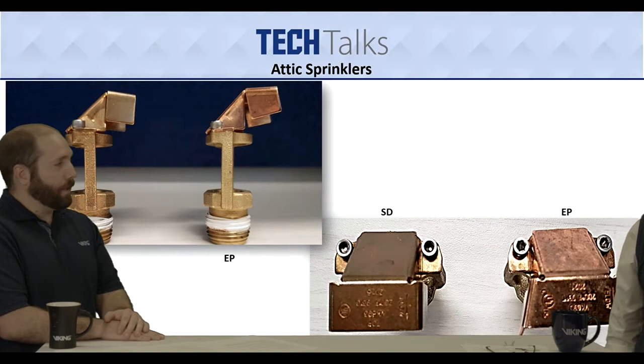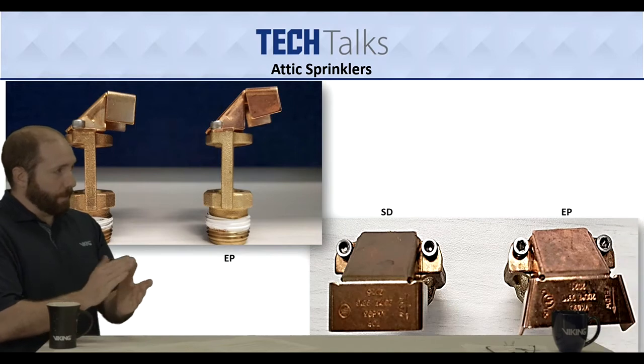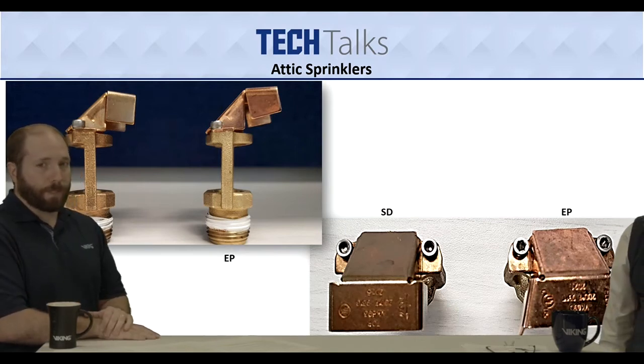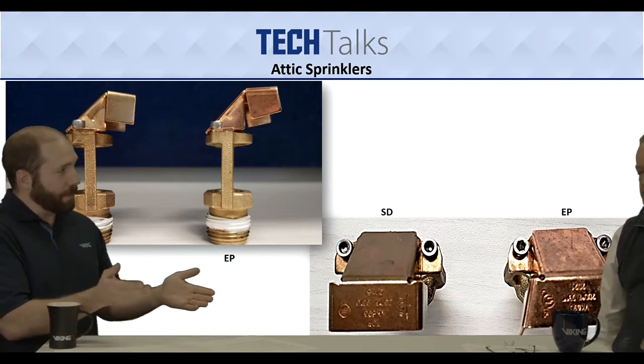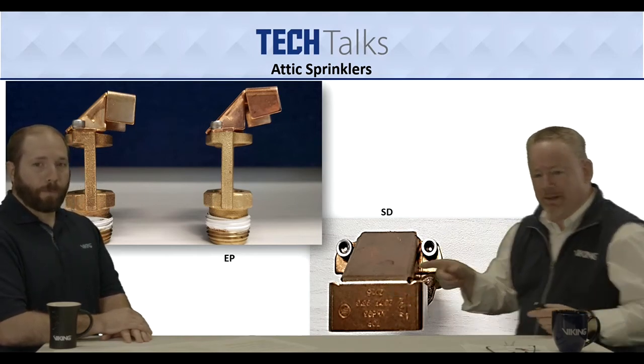The EP deflector is a little bit more elongated. And that's important because we're not actually using it at the ridge like the single directional. We're using it as a down slope sprinkler, so it's going to be positioned down the slope between the eaves and the ridge.